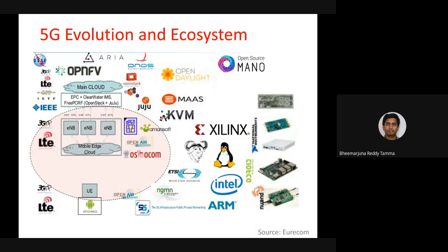Some of the base physical layer functionalities, in terms of modulation, demodulation, and channel coding, are highly computationally intensive, which you cannot do in the time limit that is available. You can offload these to accelerators. That way you can do a mix and match using CPUs, GPUs, FPGAs, and ASICs for doing the computation. And you can see on the left-hand side all the different standardization bodies and technologies.